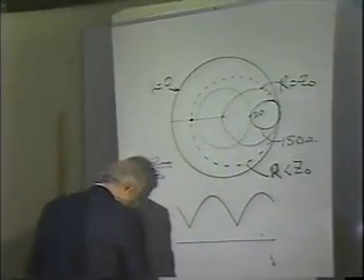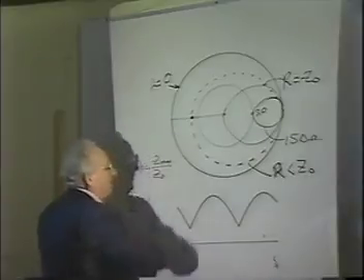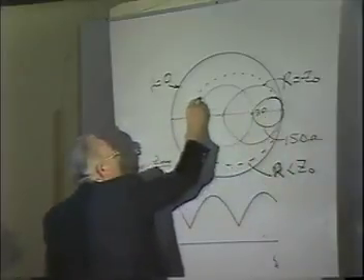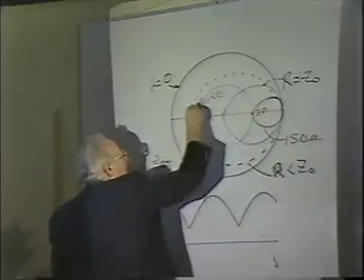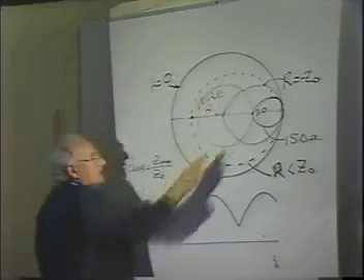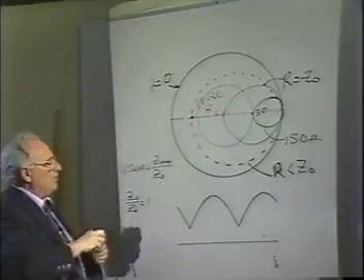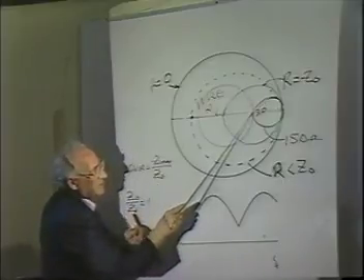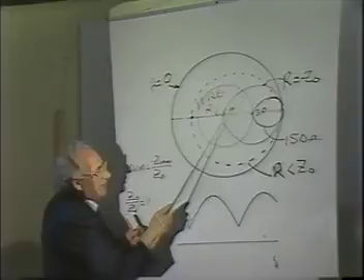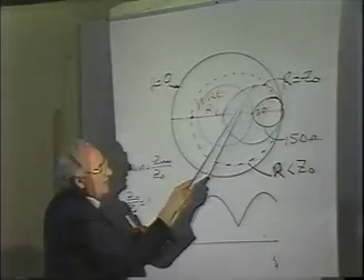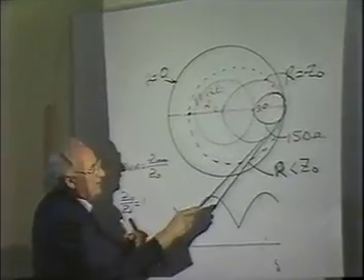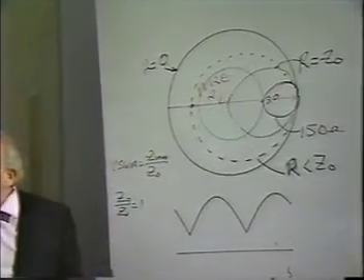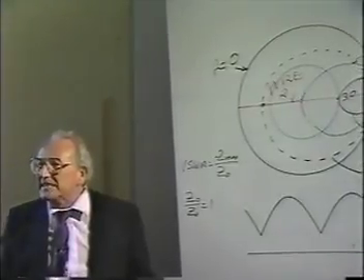We already know then that we have something to work with. At any place along this axis here, there's pure resistance. That's the only place. So here, you have a circle, 150 ohms. It's only 150 ohms pure resistance right there. Here you have a resistor circle. Every place on that circle is 50 ohms. If this is Z0, it's 50 ohms. But this one is the only point that's a pure resistance, right where it crosses the pure resistance axis.